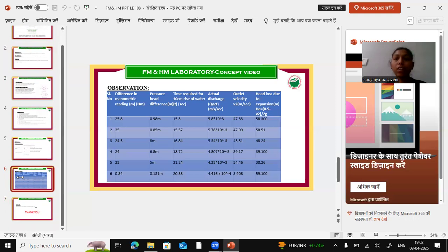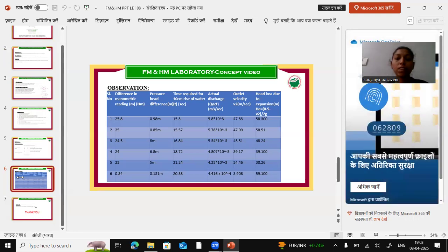The examples of minor losses are sudden enlargement, sudden contraction, pipe entrance, pipe exits, bends, pipe fittings, valves, etc. The loss of energy caused by changes in flow direction and the presence of fittings comes under pipe fittings and bends. The loss of energy as the fluid exits the pipe comes under pipe exit. The loss of energy as the fluid enters the pipe comes under pipe entrance.